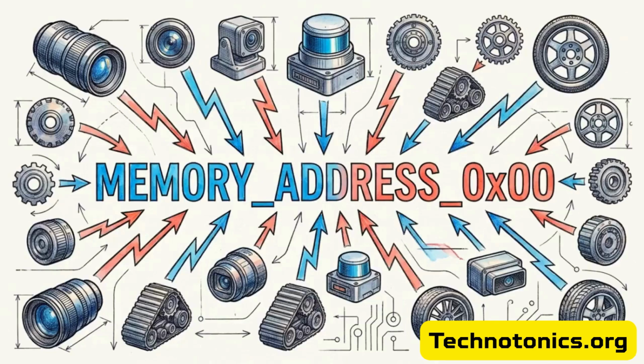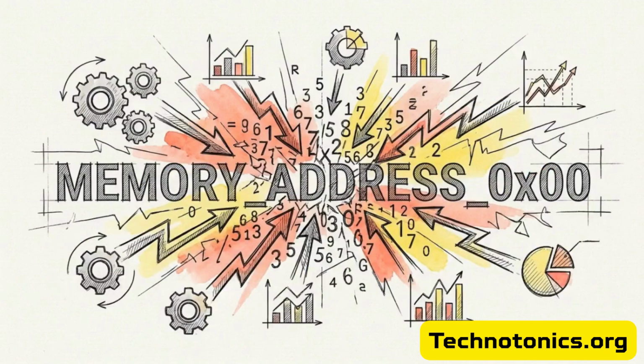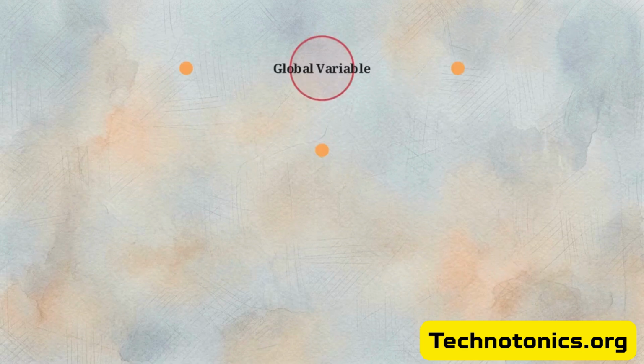Procedural ROS scripts often rely on global variables to track the robot's current position or sensor status. ROS operates on asynchronous message streams. If multiple topic callbacks attempt to update the same global variable at once, it leads to race conditions and inconsistent memory states. You can see the sensor inputs colliding at the top of this diagram.